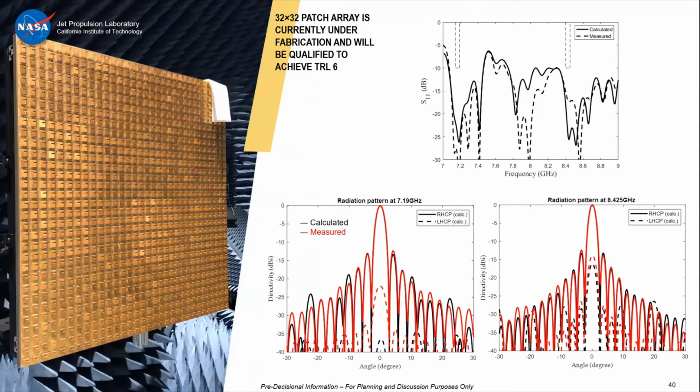We qualified the antenna by doing ESD measurement and TID testing. We put it in a vacuum chamber where we go to cryogenic temperature and we bombard this antenna with electrons. We do that so that the three-mission-life total ionizing dose is reached. And we also make sure that the rate of charging is the same as the real mission so that you can simulate the ESD discharging and the rate of discharges that you will see.